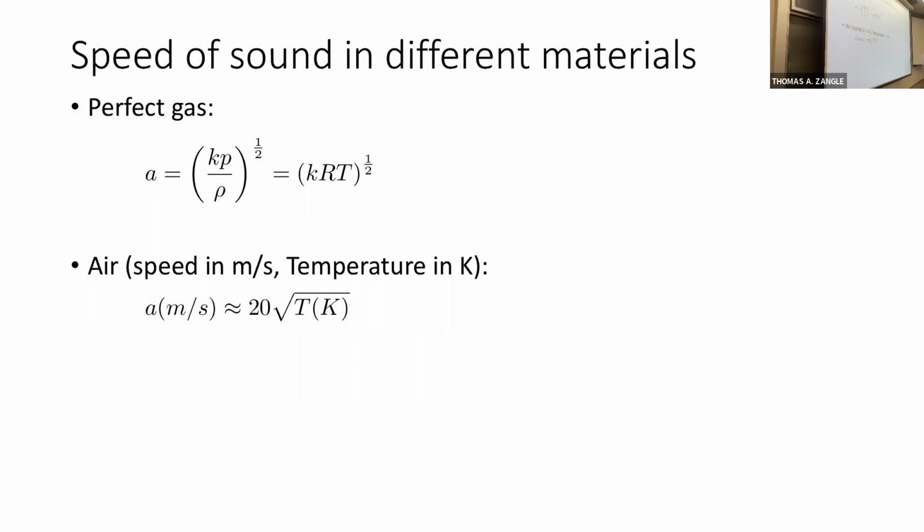Just as for external flow Reynolds number was a variable that could change as we moved down a plate, we had Reynolds number based on x, Mach number is going to be based on a local speed of sound when we're solving some problems. As temperature within our system changes, for example, if we move across a shock wave and temperature goes up, the speed of sound will change as well, and so our analysis has to include that.